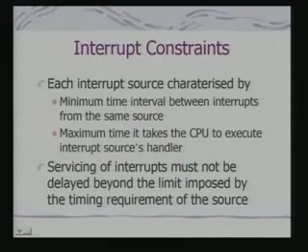And when I am inside an interrupt servicing routine, I am actually disabling the interrupt. So, if there are other interrupts occurring, they have to wait. So, when I am designing an interrupt service routine, I have to be very careful to check what? The maximum time that an interrupt service routine can take, delaying other pending interrupts. And by delaying other pending interrupts, I should not miss a deadline imposed by the external world. And this is the key issue which goes into designing an appropriate interrupt service routine.